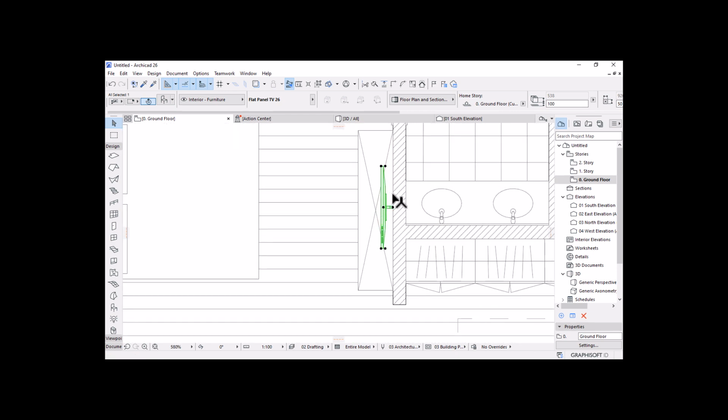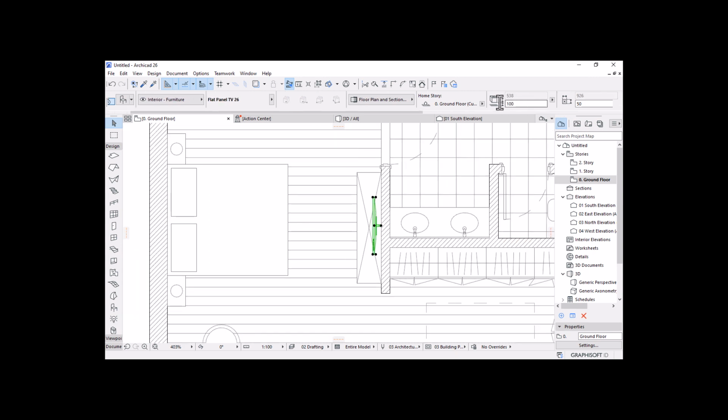You'd find on the 3D it's not sitting at the right height, because I could see here it says the base offset is 100, but the table is around 400 height. Okay, so we need to set this to be at a height of 400.